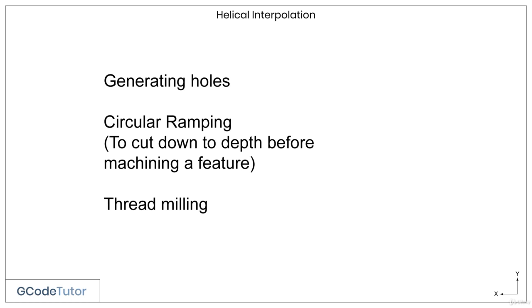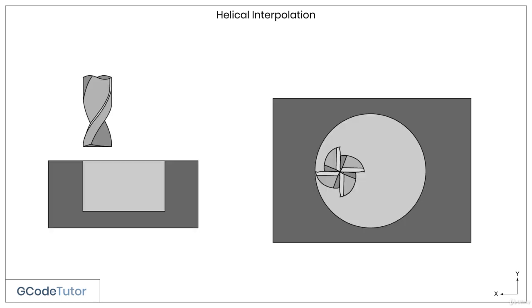So what exactly is helical interpolation? Let's have a look. Using a milling cutter, we can make a pocket, like the one shown in this diagram, by cutting in a radial move, but also in the Z-axis at the same time. So we're using G02 or G03, whilst also coming down in Z, in a spiral shape. This also explains why it's often called spiral milling.